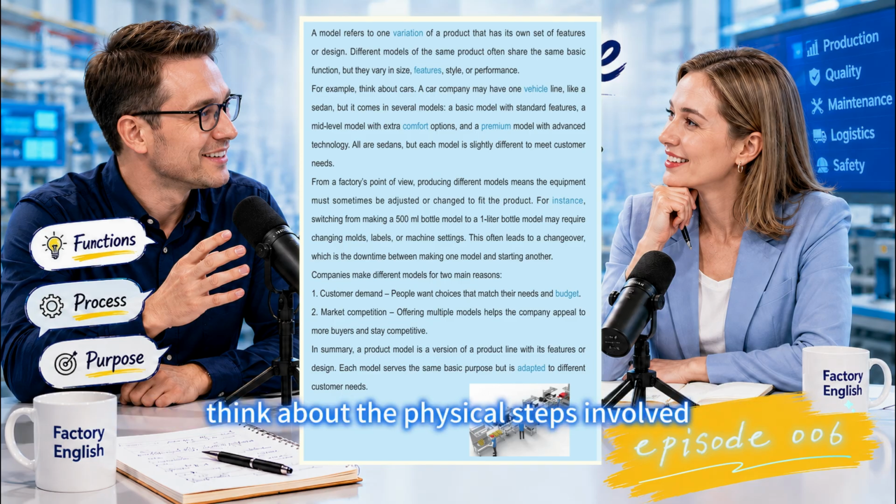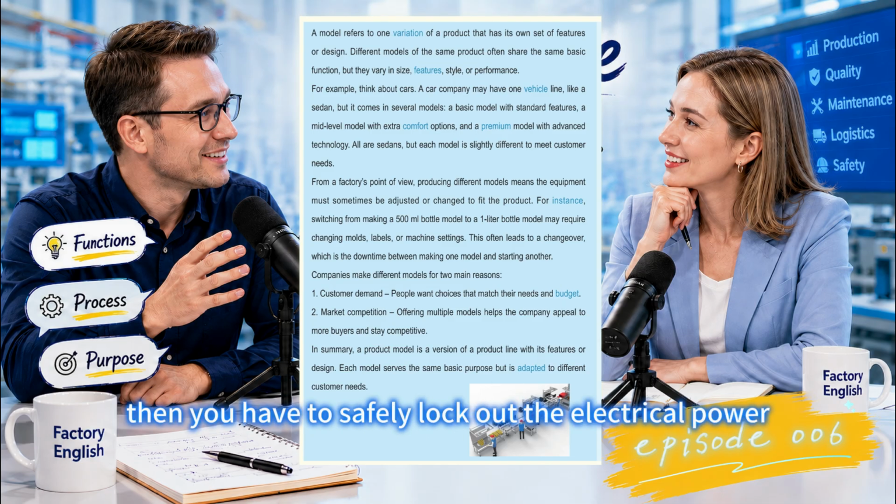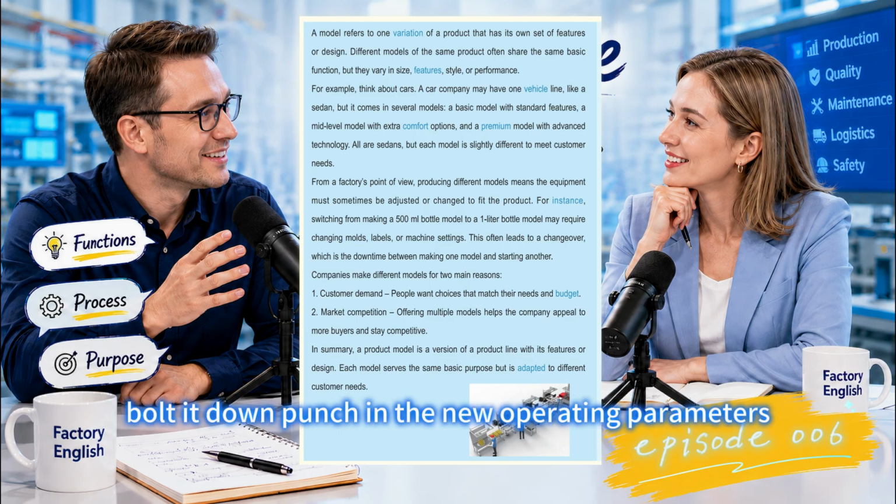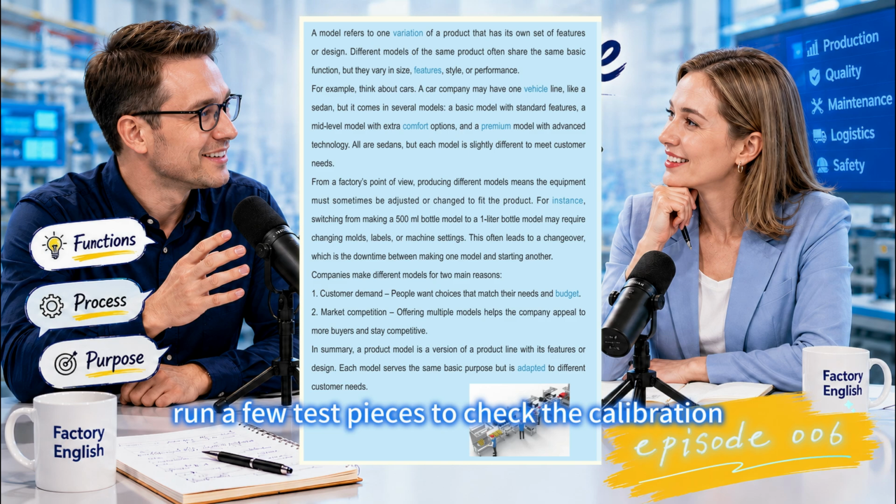Think about the physical steps involved. First, you have to purge the old raw materials out of the system. Then you have to safely lock out the electrical power so no one gets hurt. And then the heavy lifting begins. You pull the old tooling out, crane the new tooling in, bolt it down, punch in the new operating parameters, run a few test pieces to check the calibration, and finally restart the line.